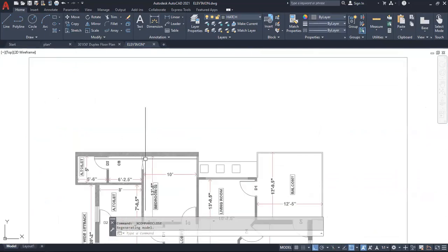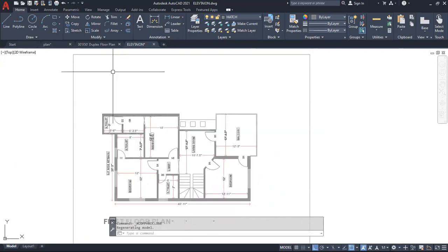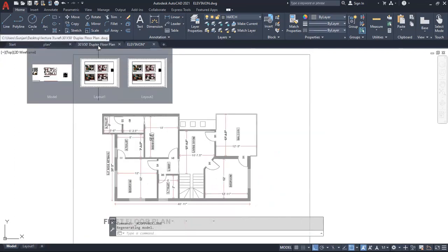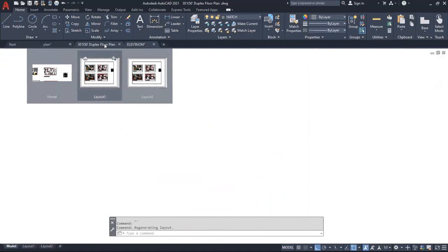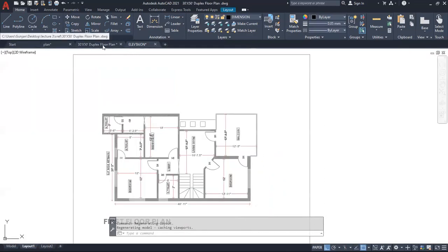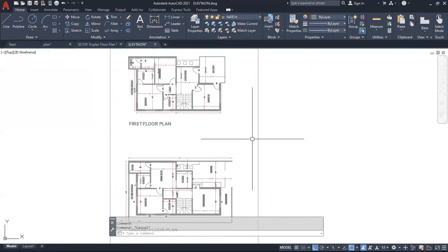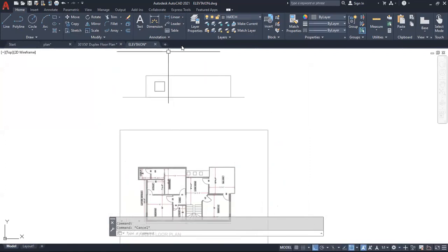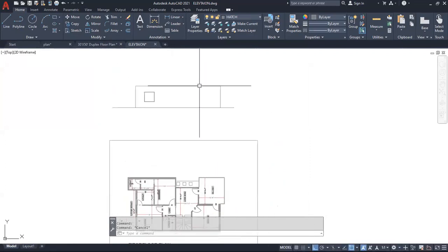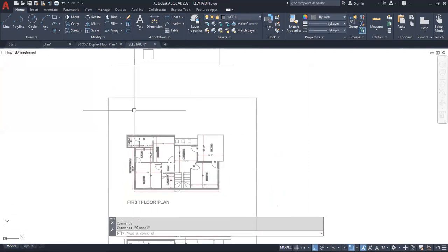It's notified me that some changes have been made to this file, and I don't need to ask the owner, the architect, to give me a separate file, to share with me a separate file, because they have made changes. It will automatically change in my XREF. And now I can make the desired corrections in my file. So this is the importance of making XREFs.